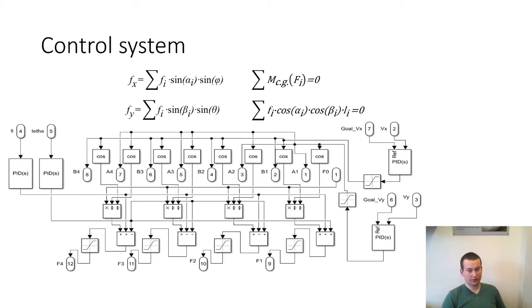As a position holding function, we add speed regulators to smooth the movements of our drone in the plane and to simplify the task of the operator. To control our drone in horizontal position, we also use speed regulators and take as errors the angles of our frame.